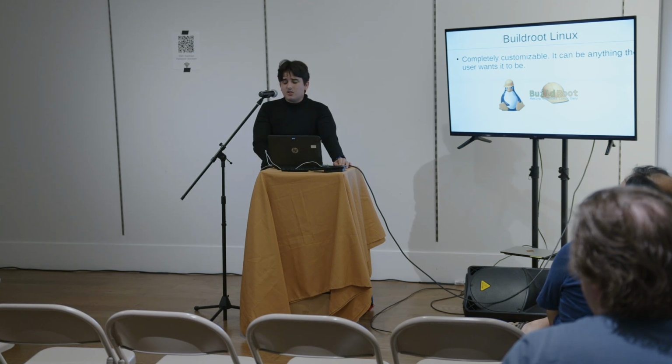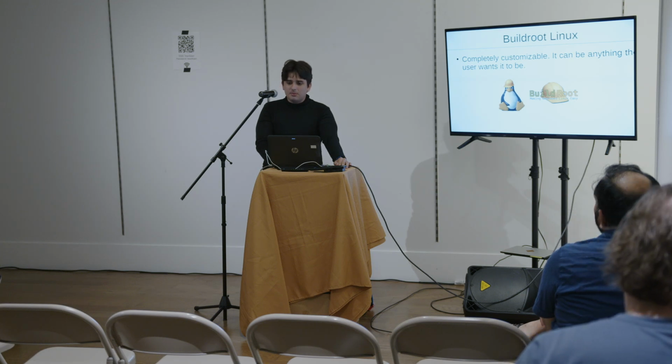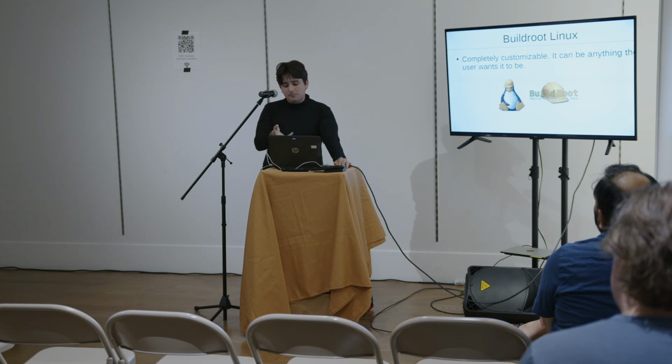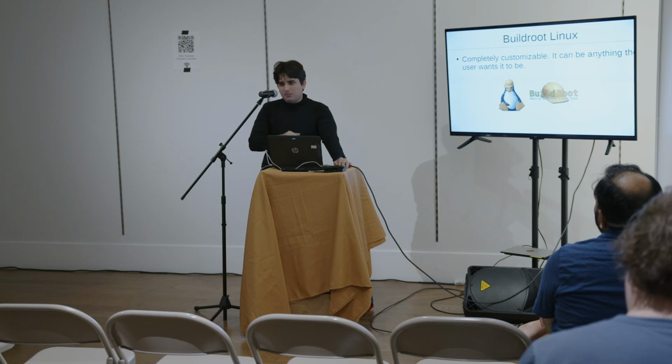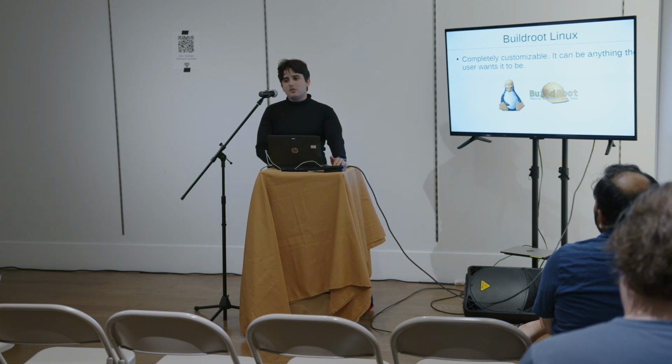So you have pretty much two options. You can either use Buildroot Linux or you can use Yocto. Now, of course, the difference between them is that Yocto is a lot more powerful, but it's also a lot more challenging to use. So we really did not know how to do this back then, and we did not want to set ourselves up for more hardships than we needed to. So at this point, we really chose Buildroot because it was simpler and easier to use than Yocto.